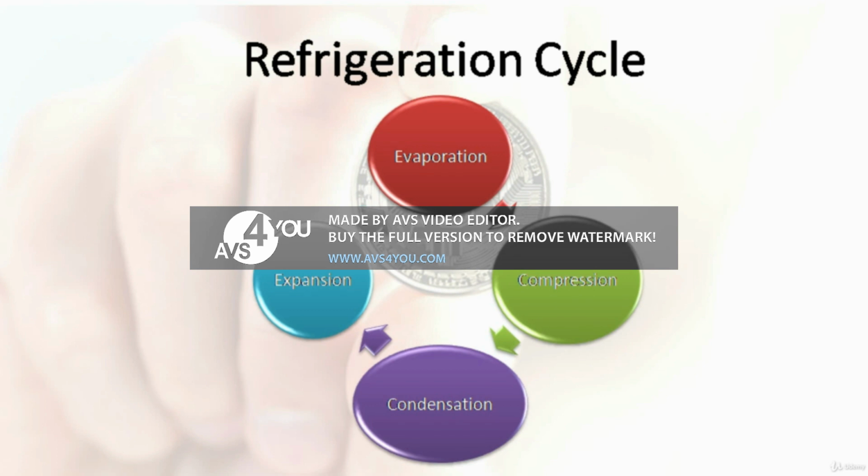Then we move on to the last stage of our cycle, which is the expansion. So even though the condenser coil has cooled the refrigerant somewhat in the condensation stage by extracting the heat, as it exits the coil, it is still a relatively hot vapor, and too hot to directly cool the mining farm. The refrigerant is then piped through a system called an expansion valve.